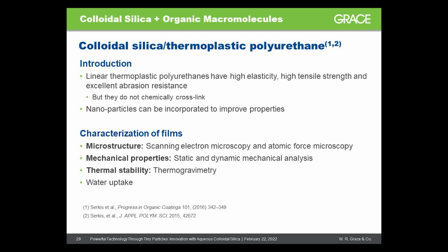The characterization of the mixtures included the microstructure as revealed by scanning electron and atomic force microscopies, mechanical properties of the films by both static and dynamic mechanical analyses, thermal stability by thermogravimetry, and water uptake.